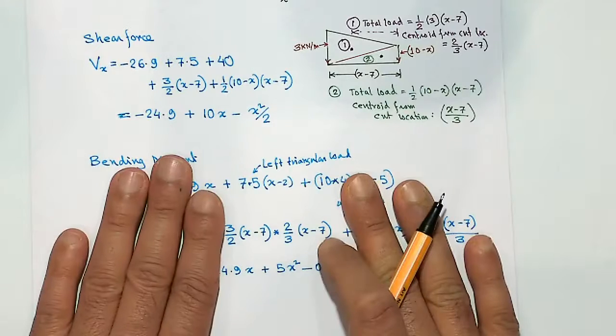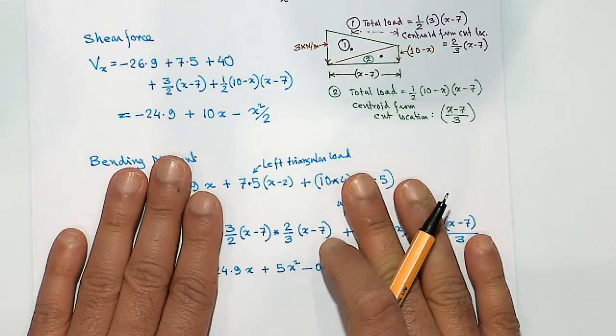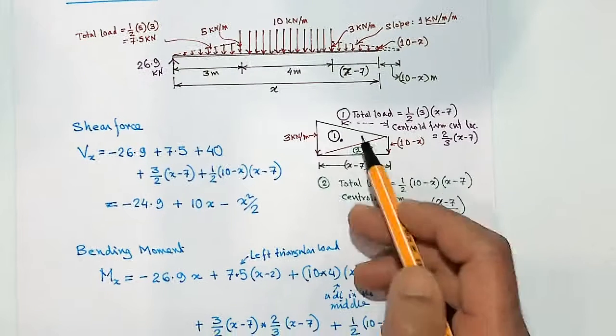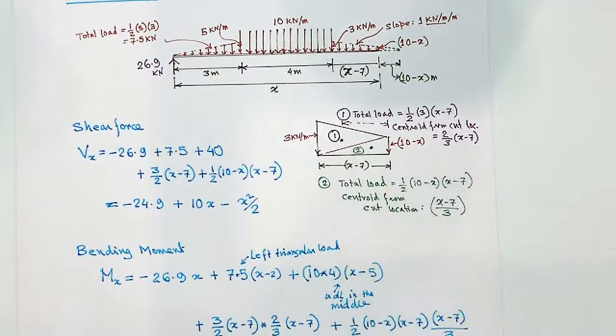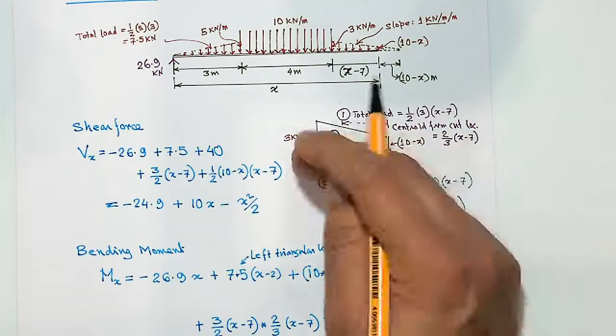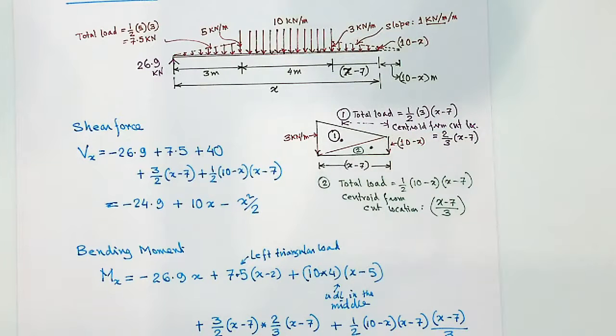Now this is fairly complicated, I am not denying that, but the point is in this way. If you have got a trapezoidal segment, instead of finding the CG of a trapezium, just divide it into two triangles, and for a triangle you know the area as well as its CG, and then you can use those two separately. Who asked this about the trapezoidal? Is that okay?